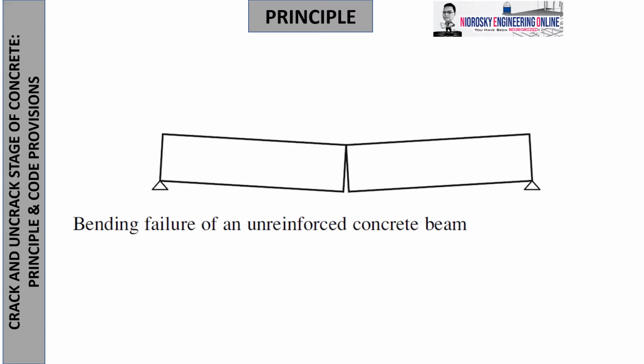However, due to the property of concrete that it is brittle, there will be some magnitude of force W or uniform load that may potentially produce breaking or cracking of the beam. So there will be a point in question: when will the beam crack? Will it be the property of the load? Will it be the property of the concrete itself? Or what kind of serviceability condition are we going to observe? Well, deflection is one, and the others are, let's say, shrinkage, creep, and so on.